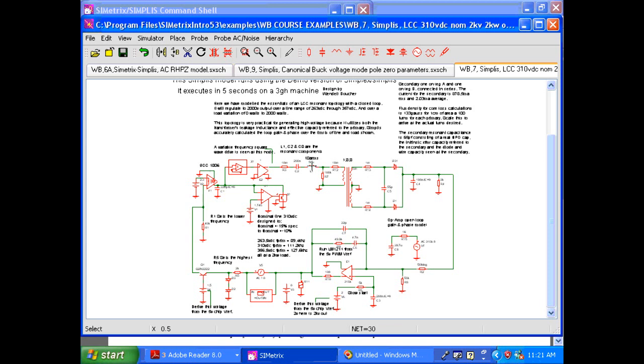That's the L. That's a C. The other C is a reflected C in the transformer. It's a step-up transformer, 1 to 8 to 8. This is the load capacitor and load resistor. We come back here and we sense the voltage and we measure it. This is a compensation amplifier, type 2. Come back through here. We modulate at this point. We convert this DC modulation to a frequency modulation by simulating this 1806 chip. I'll expand this now for you.